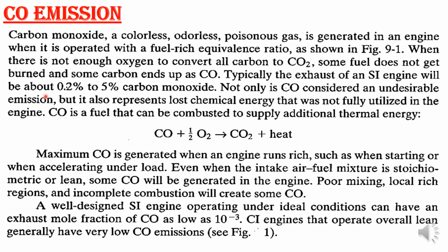But if the availability of oxygen itself is less, then our air-fuel mixture is in a richer region because of insufficient oxygen as well as insufficient time. Two conditions are there for the formation of CO: one is insufficient oxygen, and one more is insufficient time. Because of that, incomplete combustion will lead to the formation of your carbon monoxide.